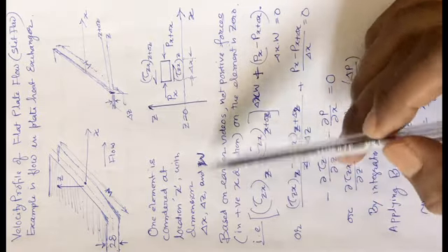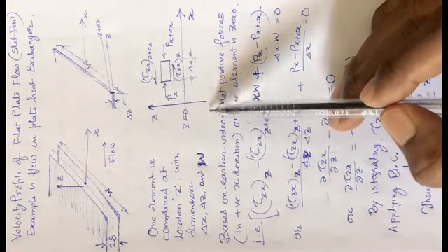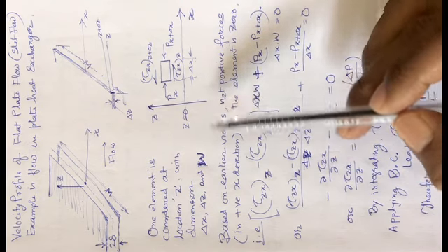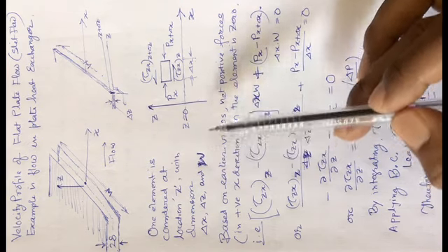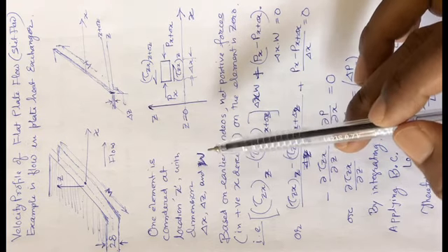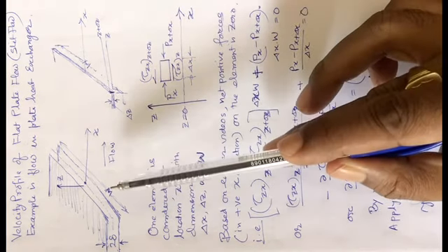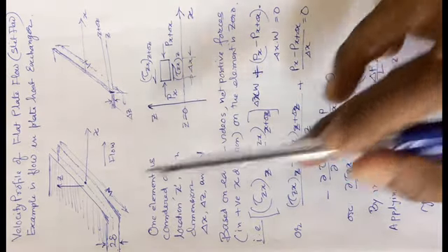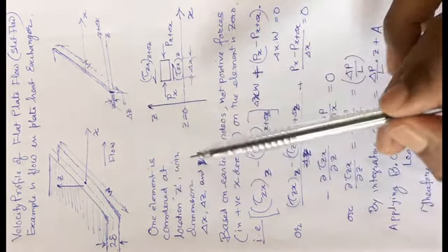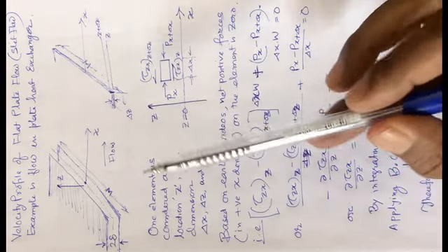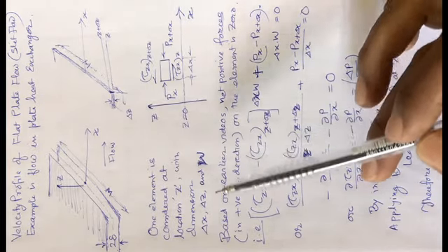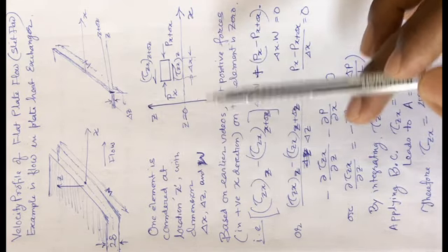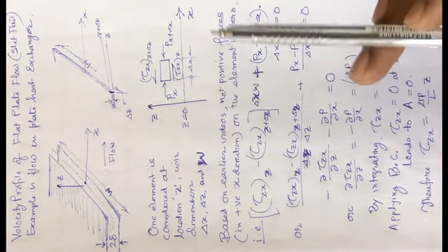Now you see, this video we can see in context of the earlier videos as well, one for the horizontal pipe flow and another one for falling film, where we had that width of W. However, in case of falling film the flow was happening due to gravity, and in this case it is pressure flow, just like while deriving the Hagen-Poiseuille equation.